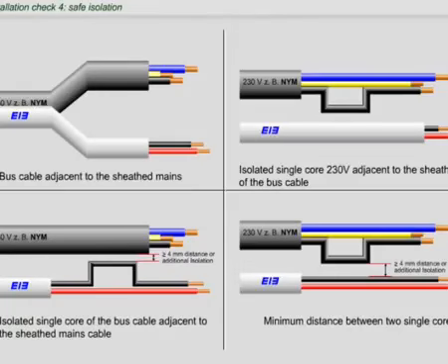When running a visual check, the isolation of the EIB KNX network and other networks must be tested. Also, in distribution boards, the installed bus cable must be sheathed.